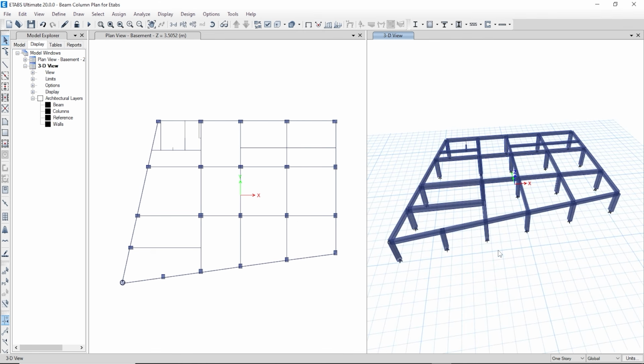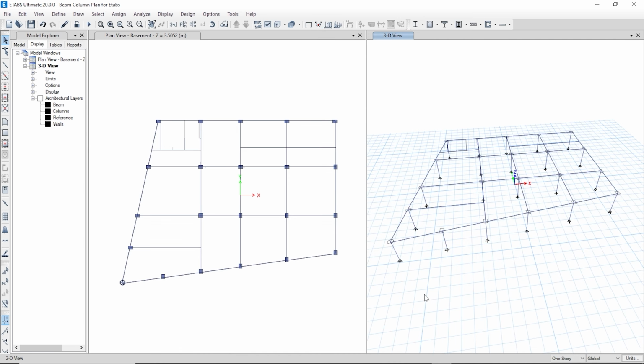Before we move on for creating slabs and shear walls, a necessary habit that you should develop as a professional design engineer is that you should check the stability of beam column portal frame. It is very important to know early on which beams are falling, which are not supported by columns. Once the slabs and shear walls are placed, you will not be able to see which beams are falling, as it will be supported by slabs, and it will lead to miscalculation of loads. So straightforward, hit the analysis button to check the stability of this portal frame.